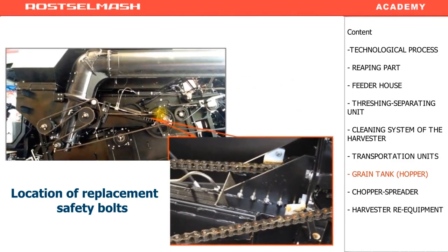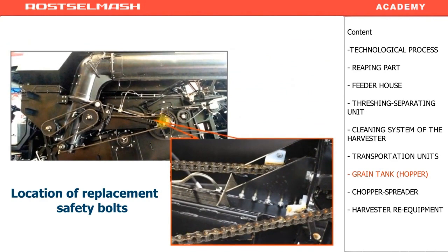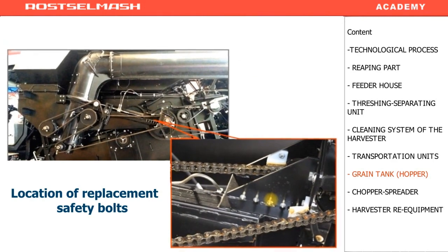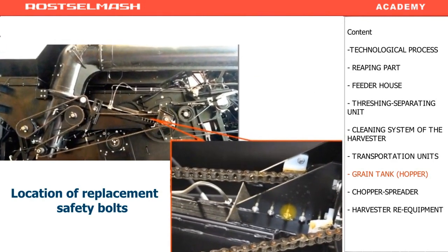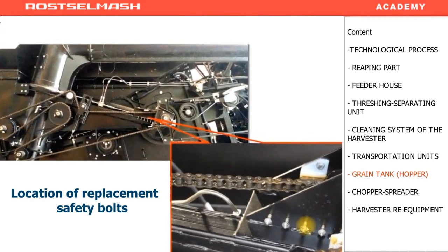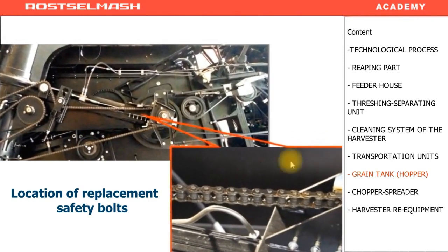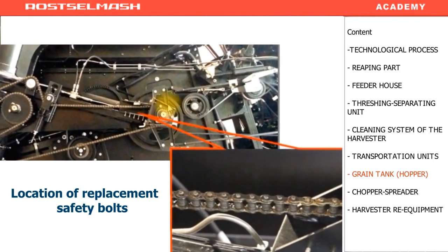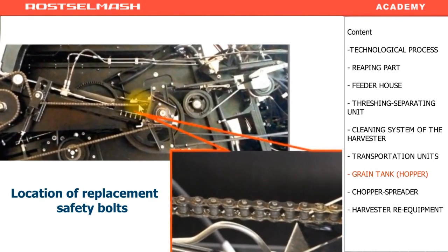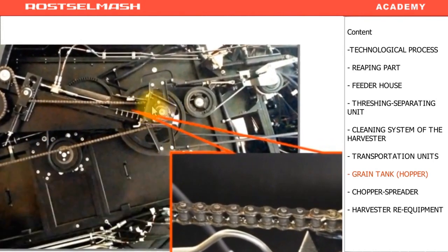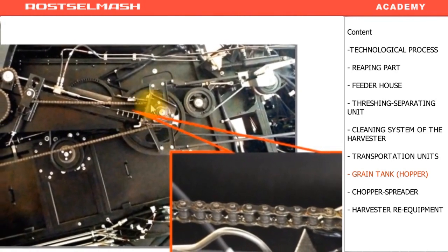It is located on the shaft. There are 2 discs which are connected with the shear bolt. In case of overload, the shear bolt is cut. One of the discs still rotates. The belt rotates the pulley. The other disc, which is geared with a sprocket, does not move. Unloading is not driven.